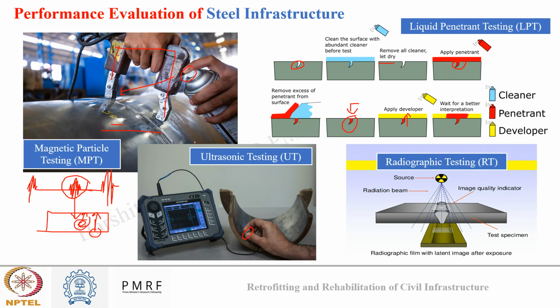So the area with defects such as crack, voids, and inclusion, they will attenuate this radiation differently, resulting in variation in the transmitted intensity. So if we place a detector on the opposite side of the steel to capture the transmitted radiation, we can see a radiographic image.